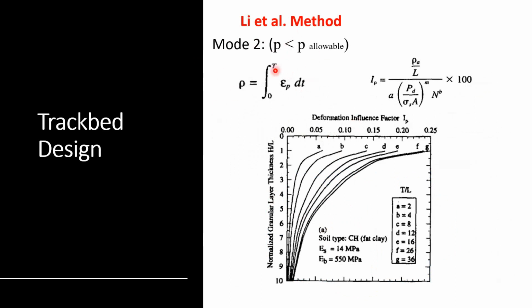Equations here for the plastic strain. The way they deal with the plastic strain is a little bit conservative. If you try and solve the same problem using a finite element analysis, you will realize that the plastic strain is usually conservative because they just link the strain to the thickness of your subgrade material. And again, as a geotechnical engineer, you're the one who can decide on the effective depth of influence of your embankment. So how much would your T, like the subgrade thickness,